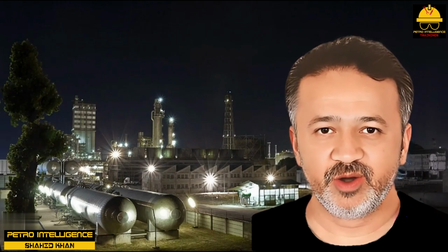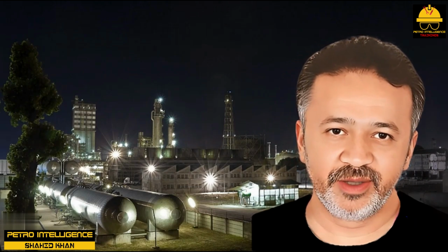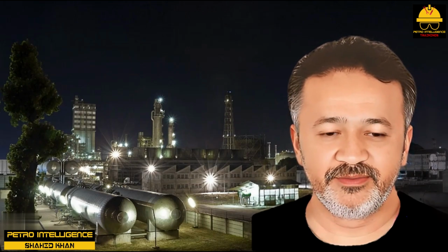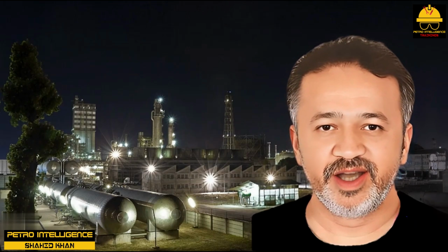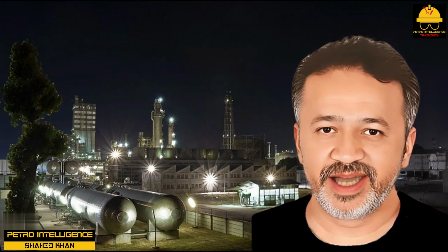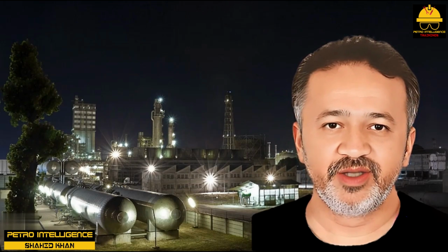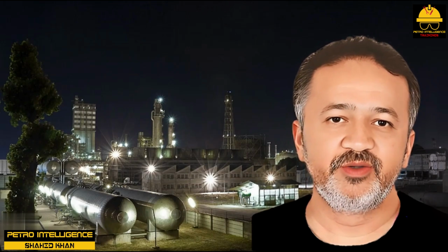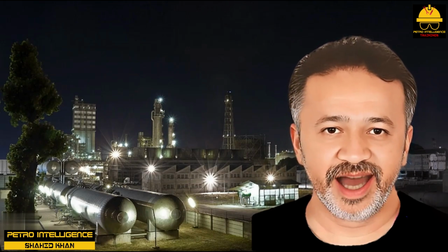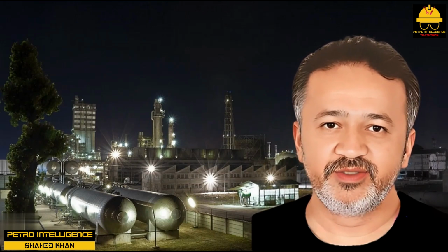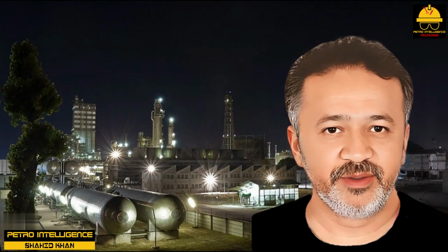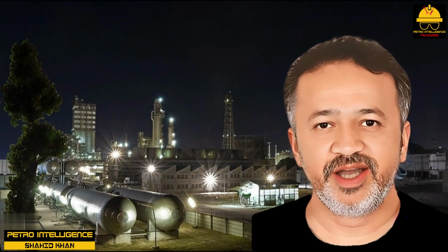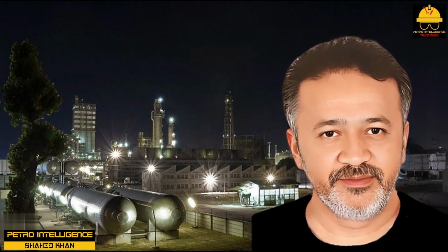Steam hydrocarbon reforming. This is also an endothermic process. The reaction takes place inside catalyst-filled furnace tubes. Heat is supplied to the tubes by furnace firing. Almost any hydrocarbon can be used: natural gas, propane, butane. The objective is to make hydrogen. Most of the world's hydrogen is produced in this way. Half the hydrogen comes from steam and the other half from hydrocarbons. All of the carbon in the feed is converted to CO2 and vented. How hydrogen-powered cars will help global warming, I do not grasp.